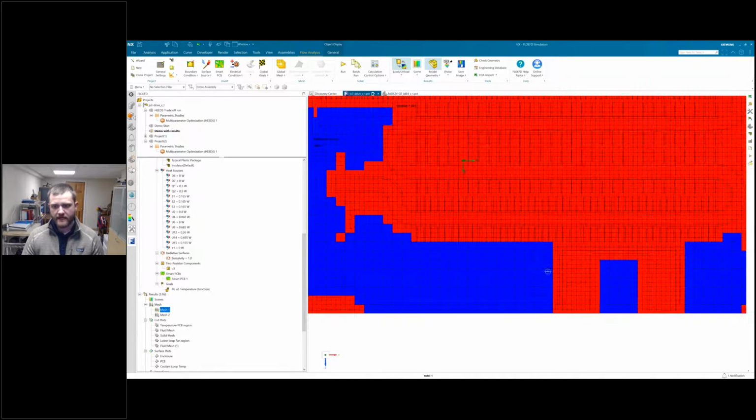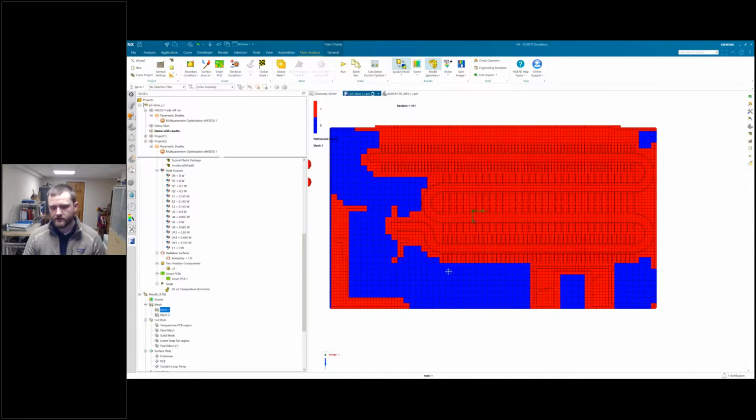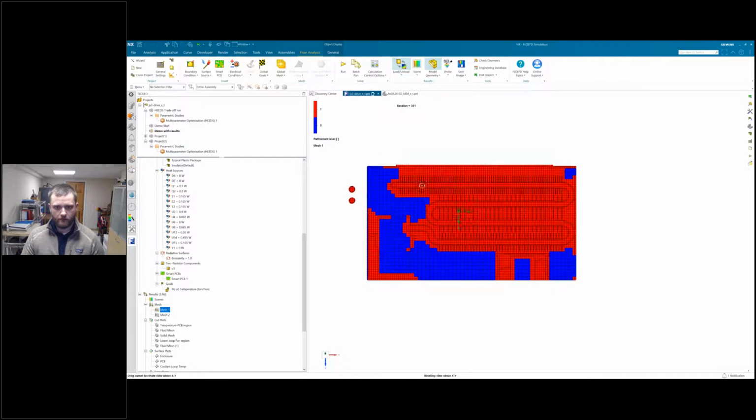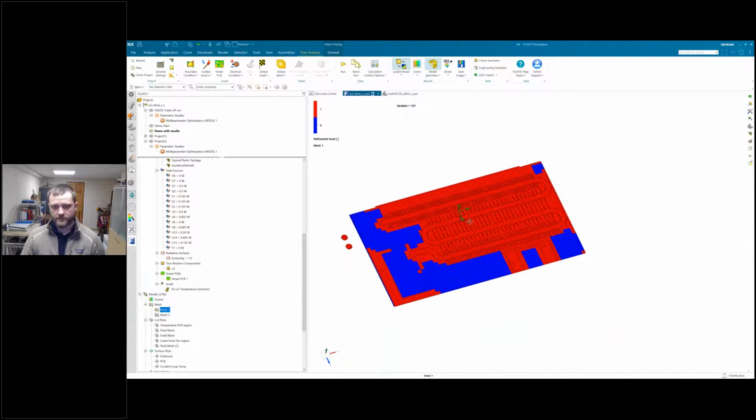And you can see that we have some refinement. This first level mesh actually looks like it was done on a level 4, not a level 3. And this is a level 4 mesh to start. And then in these areas, it's refined down to 1 level of refinement. And this is done, as I said, based on curvature, passage space, and what else? Possible fluid solid interaction, etc.